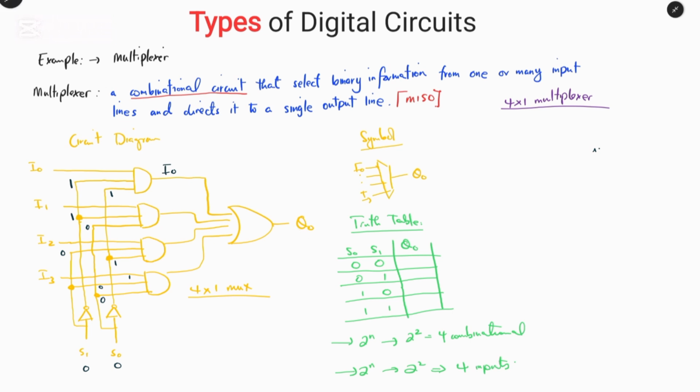So we can see that the output will only accept one of the inputs at a time. From this AND gate, since we have 3 inputs, in order to have high on the other side, all the inputs must be ones. If one of these has a binary of zero, then the output will be low.